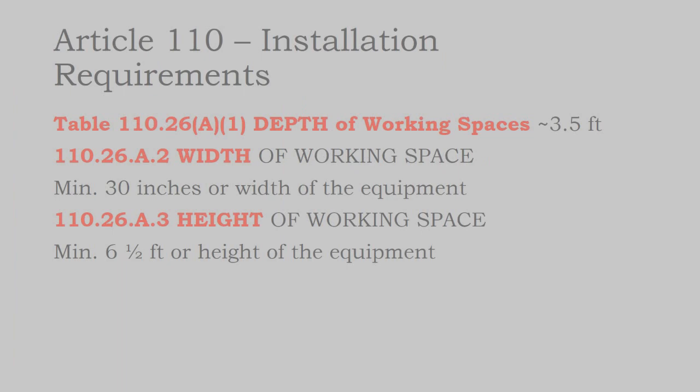Generally, if you're a commercial electrician, you have more rigorous oversight by the state and you're dealing with higher voltage systems, 480 volts instead of 240 volts. Solar arrays can go even higher than that, but not always are they being installed by electricians on the job site. And so the depth of the working space, how far back does the equipment need to go?